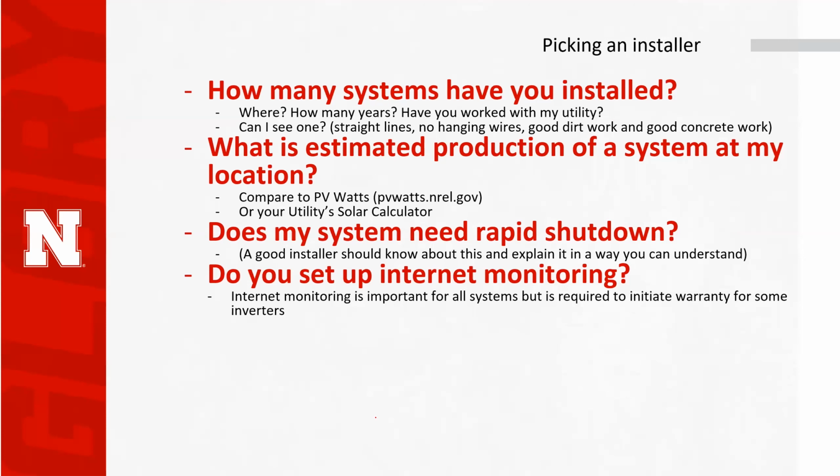Do you set up internet monitoring? Remember how important internet monitoring is. Internet monitoring is critical so that you can know when your system is up and running properly, when it's broken down, and also because it can initiate the warranty on some inverters. So it's really important. If you have a system where internet monitoring is difficult, I understand. Work through it.